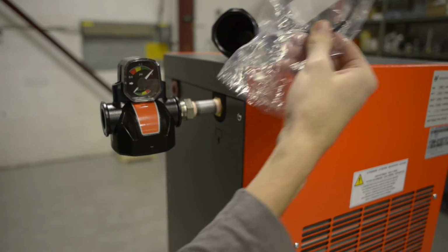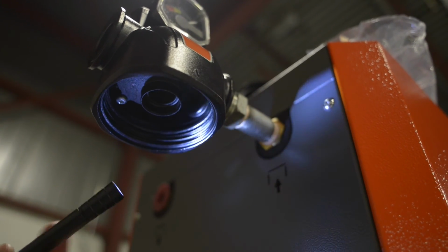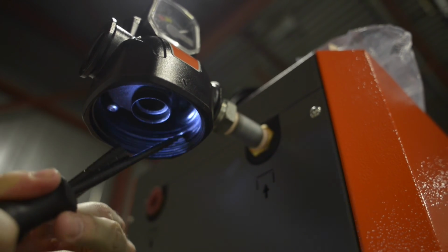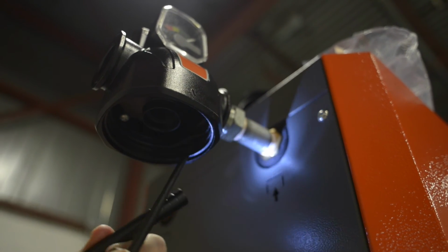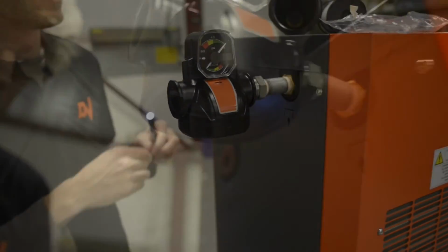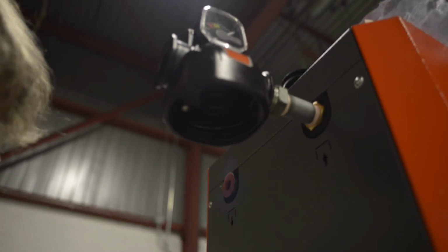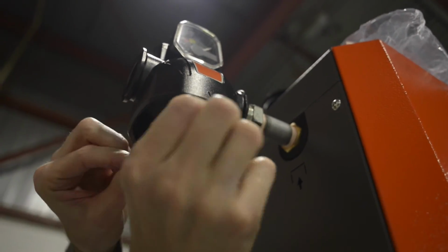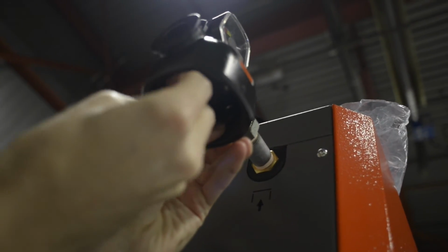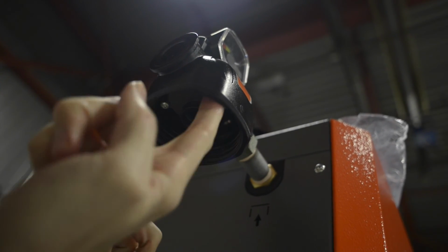Each filter comes with an O-ring that you can replace on the inside of the filter head. You see it there, you can just use a small screwdriver and pop out the O-ring just like so, and you can replace it. You can use a bit of grease on the O-ring if you like, and then it'll just sit up inside the filter head. There's a seat there. You wouldn't want to put it on the body because it may get crushed and misaligned. So you want to make sure it's seated up into the head like that.